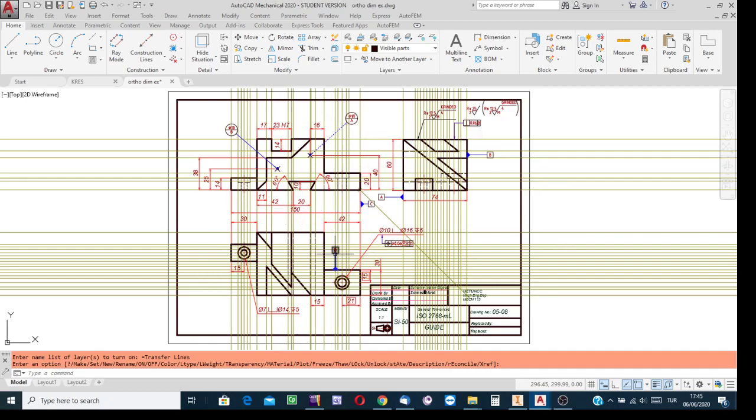Similarly, in engineering drawing, everybody should know that this is the front side view, this is the top side view, this is the left side view, and so on. If they have been constructed using the coordinate values of the characteristic points as the same on the adjacent picture planes, and the views are at their correct places, then the person can be expected to read the given views and imagine the object in the mind three-dimensionally. View reading, in short, is learned naturally, inherently.